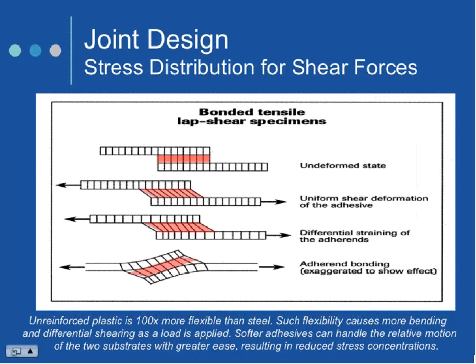So, just looking at that a little closer, again, in the still shot, what you're seeing is the bonded assembly, the red's the adhesive. Notice as we start to place that shear force, you see the stretching of the adhesive. It doesn't look like a perfect little rectangle anymore. And in this scenario, you can see now the substrate starting to stretch. And as the force is really placed on it, you can see we're actually moving into a peel mode.